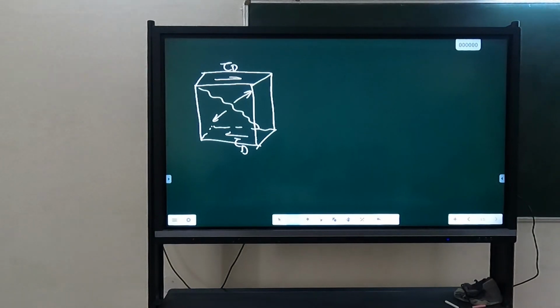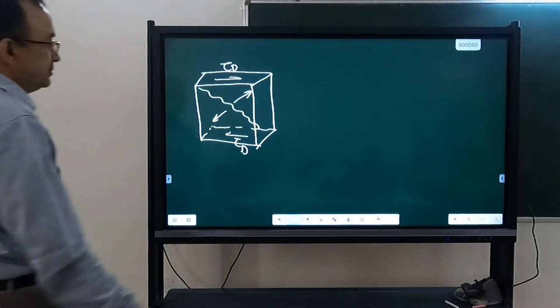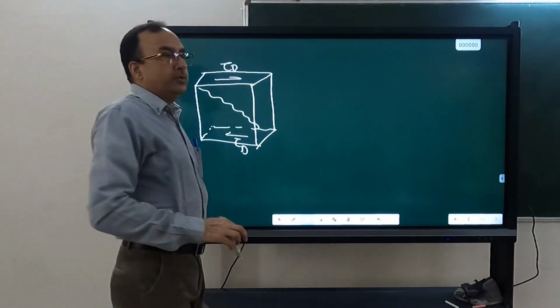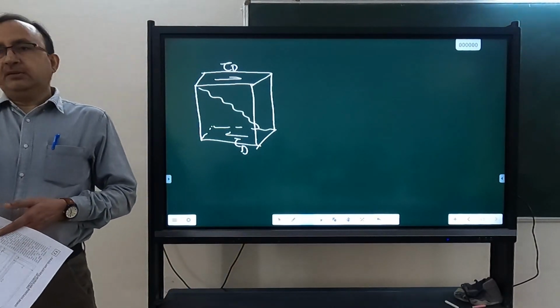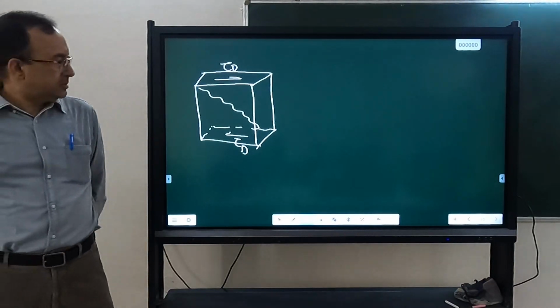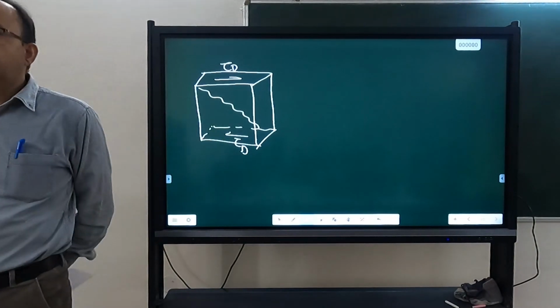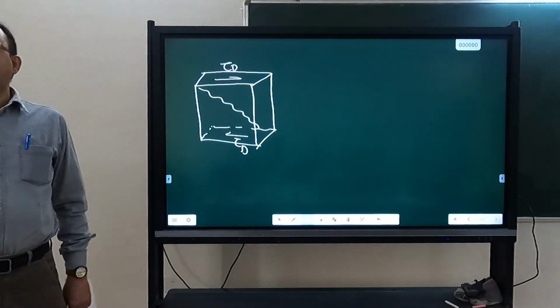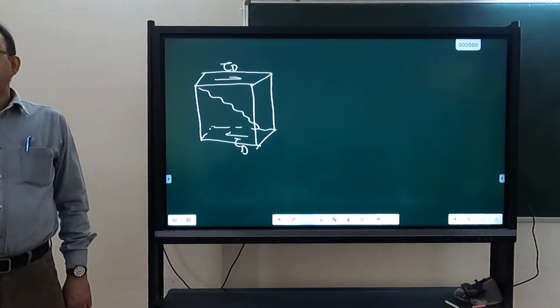Sir, the action is along this surface sliding, means the reaction is getting from the diagonal element, so action and reaction must be in one plane. The force I am applying here, I will measure it, and that will be the demand on that pier. But the reaction is coming from the diagonal. No, the reaction is coming here, not from the diagonal. Failure is occurring along the diagonal, but the reaction will be here. If I am applying a force in the horizontal direction, what will be the reaction? Horizontal. Reaction cannot be diagonal.